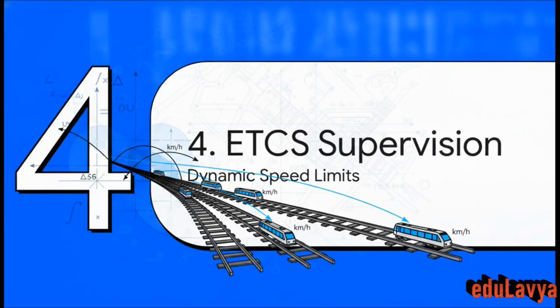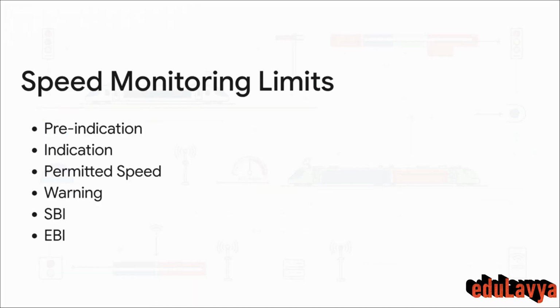Let's move to Section 4, ETCS train supervision. Let's look at how this mathematical braking model is practically applied in our modern interoperable networks. In ETCS Level 2, dynamic train supervision means the onboard computer is constantly comparing the actual speed against several heavily calculated limit curves to enforce what we call the most restrictive speed profile, and it happens through a very strict escalation sequence. It starts off mildly with a pre-indication, just to warn of an upcoming braking zone.